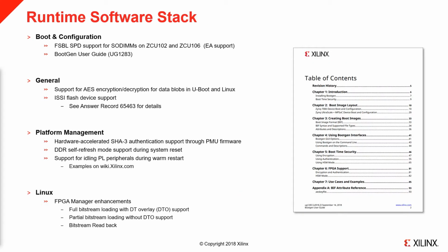Our embedded software stack has been updated in a number of ways. First, we have made updates to the Zynq UltraScale+ MPSoC first stage bootloader to read SPD data from SODIMMs. This support is currently in an early access state and works on the ZCU102 and ZCU106 boards.